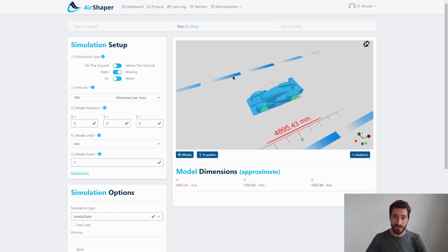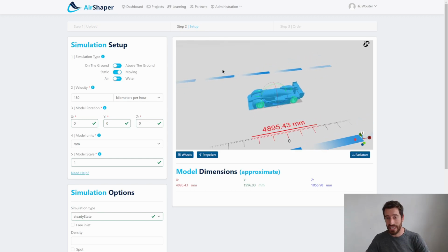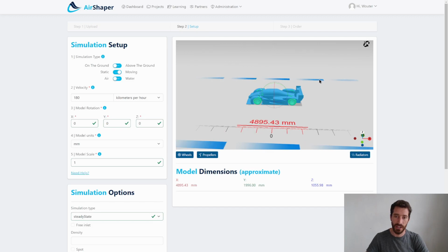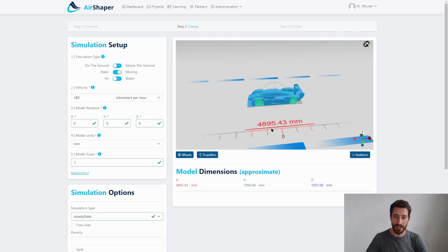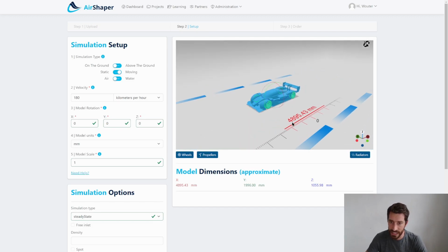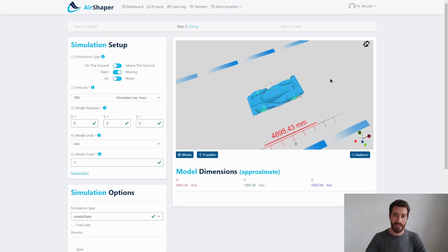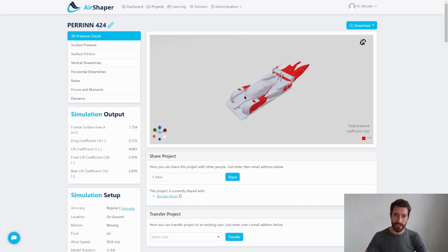We have adaptive mesh refinement, which I'll get to later on, to automatically refine the mesh after the first simulation based on the gradient of pressure and the vorticity. We will refine the wake of the car. We will refine high pressure gradient areas like the leading edge of airfoils and so on. So all of that is automated, and once a simulation has finished, you get this.